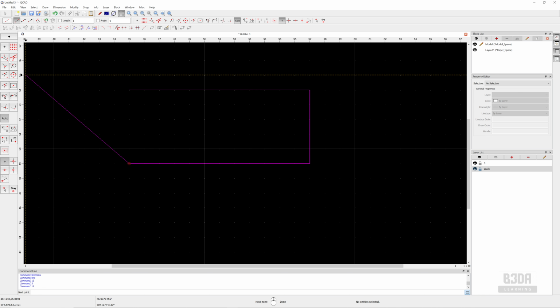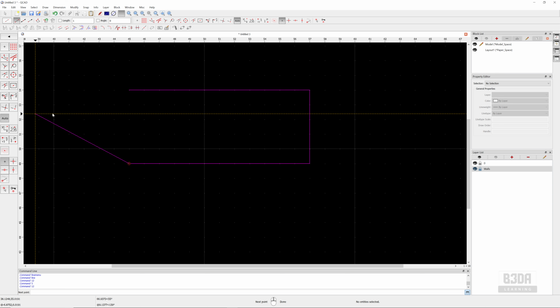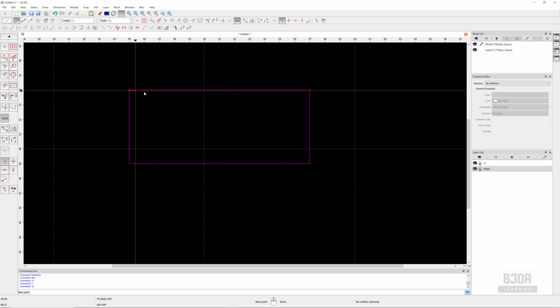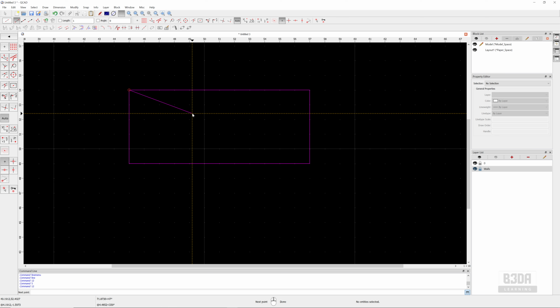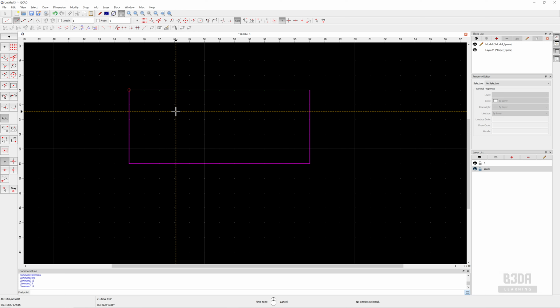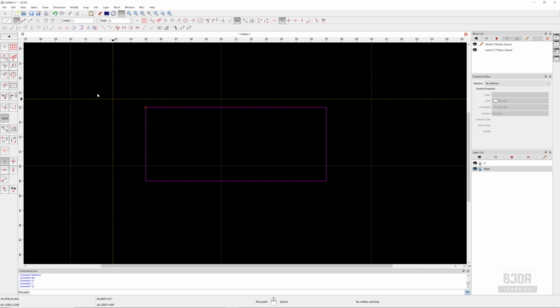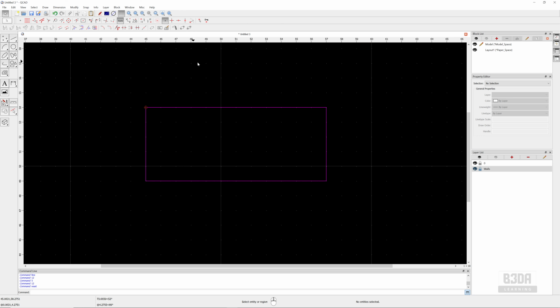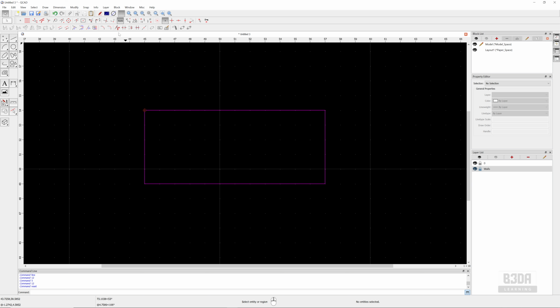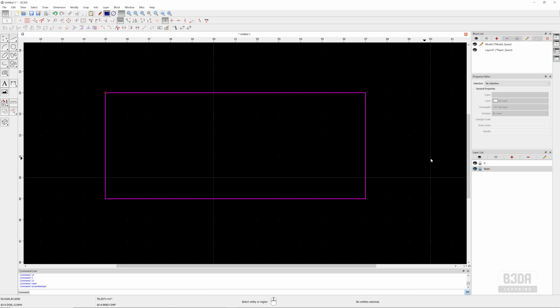You can see the snaps that I can choose. It's actually in auto mode, so QCAD will try to guess what is the best snap for me. Press enter or right click to finish your drawing, and we have our first set of lines. I can press this button here so we can see the line weight based on the layers, and we can use now an offset.